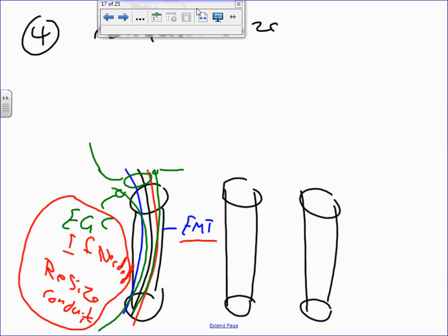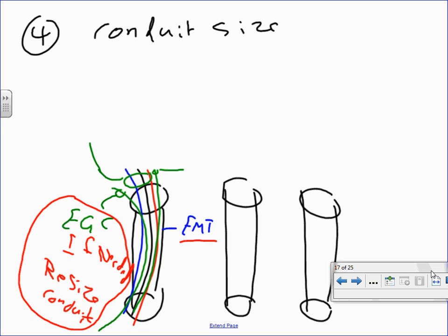Okay, so let's go size, gentlemen. We're going to size the conduit. Now for the conduit, I'm not going to go to the tables. You guys know how to go to tables by now, I hope. We're going to do the calculation and you guys will verify it. I have 3 conductors, remember, so we have feeders, 3 conductors, number 400 kcm THHN.